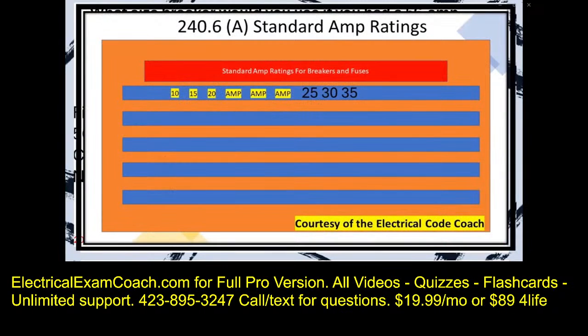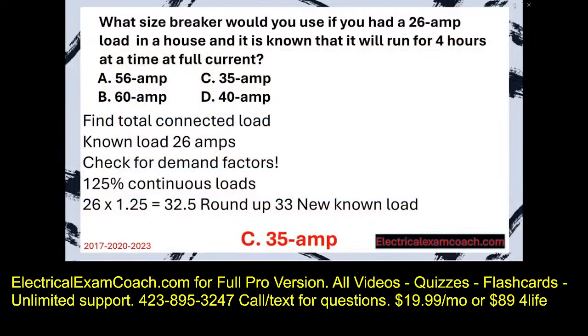Then we head to Table 240.6(A), and we choose the next size up. And in this case, it's going to be a 35 amp breaker. Great job.